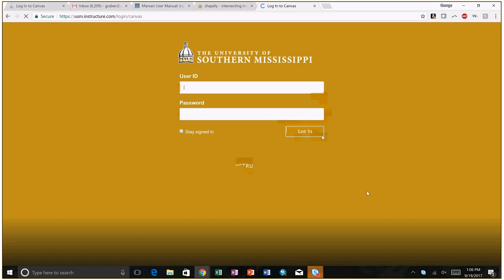If we were to look at different types of devices, here's a Garmin with a wide area augmentation system receiver in it. You're going to get down to about 2 meters. We'll talk about what WAAS is in a second. Here's a Trimble GO3, which is a nice system. This is just the raw data, 3 meters. If it's post-processed, we'll talk about what that means.